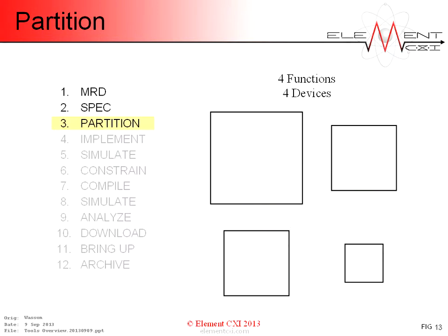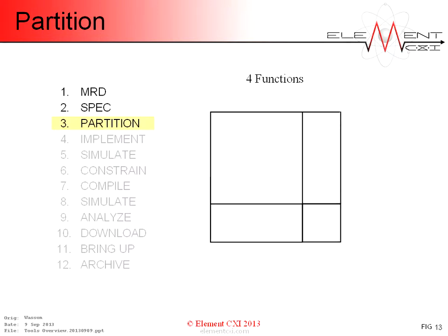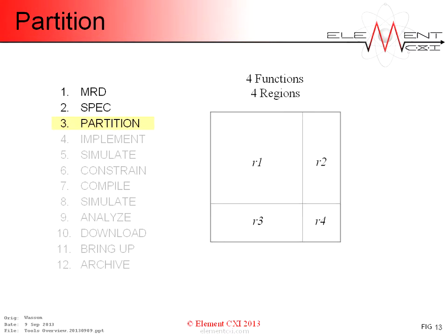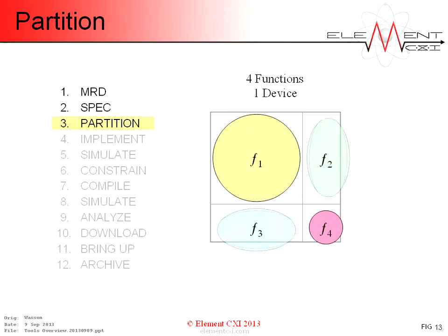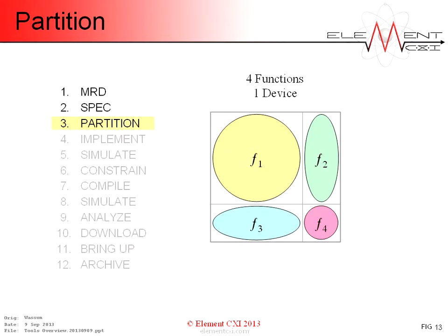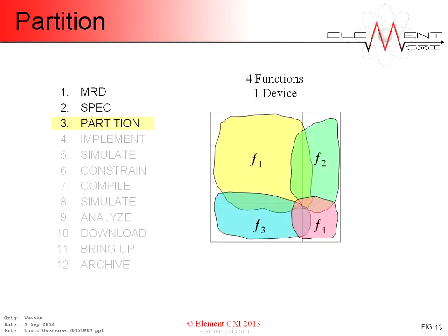And this was how it was done when devices were small. But with increasing part size and resource availability, integration into a single device becomes practical, with this internal partitioning manually defined by user-supplied constraints. It's worth mentioning that one of the vulnerabilities of partition integration is the degradation of individual function performance because of the inevitable competition for overlapping resources.